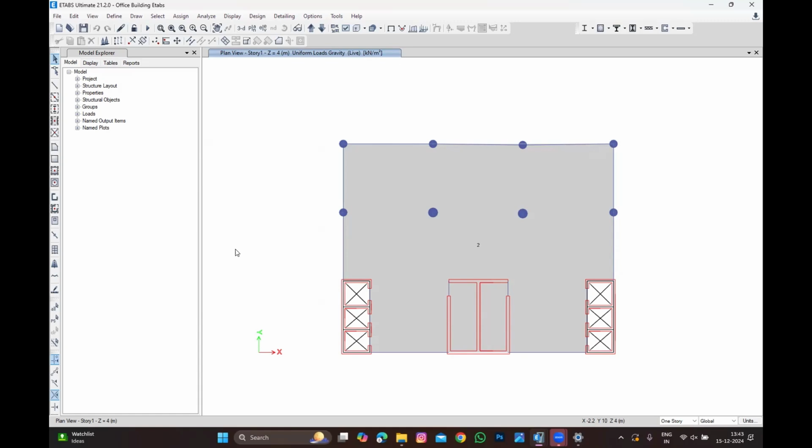If it is 8 plus 6, say if you are going for 9 plus 9, different glass, right? Actually, maybe you're going for spider glass, then the glass thickness will be more, right? So DM is going for a higher end. Actually, go for 3 kN per meter. Okay, but glass cladding, including only that, you're taking 10 to 15% extra for mullions and transoms. That's what you took, like 14 millimeter glass for the density.